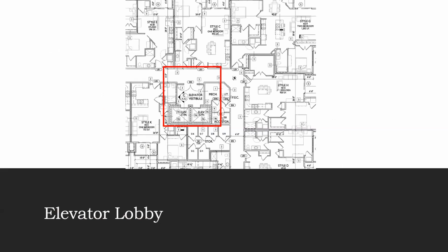And so on the screen, you can see that there are two elevators. There's a pair of same swing doors. They're creating that lobby space for compartmentalization. So if those doors were tested to UL 1784 without an artificial bottom seal, then they would be compliant.